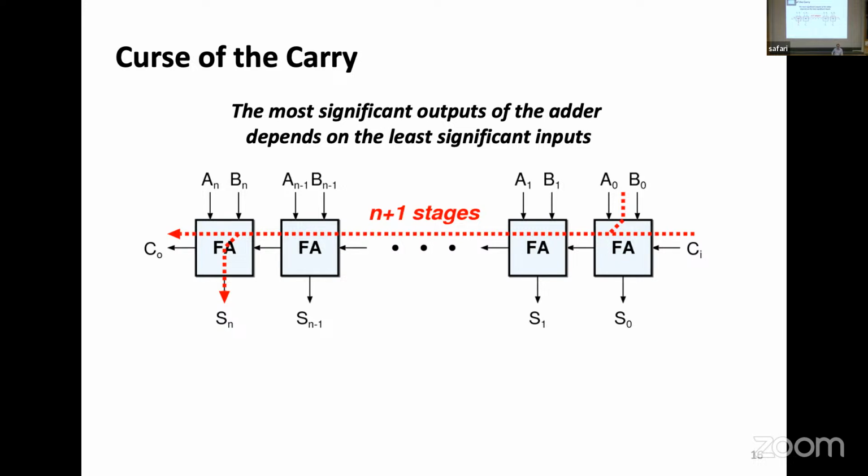Yes? Yeah, it's a good question. Why do I care about it, right? This operation takes long. We didn't see it yet, but in the next lectures we are going to talk about sequential circuits. In sequential circuits, we are going to divide the operation of our circuit into time units. At every time step, we want a certain operation to finish, and we will leave enough time for this operation to finish. If it's a processor, we are talking about the clock frequency, meaning how many times I can do a certain operation within 1 second. So if this operation takes long, I have to give enough time within the clock period so that this operation can finish reliably.